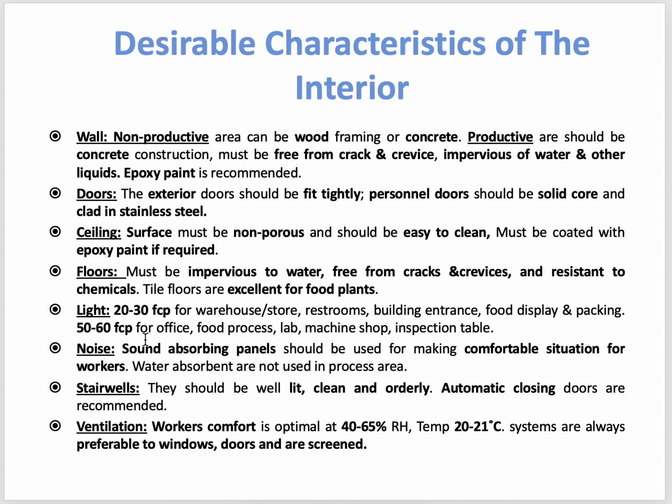Okay, then floors of the plant. Floors must be impervious to water, free from cracks and crevices, and resistant to chemicals. For a food processing plant, tile floors are very good. Tiles are a good choice for making the floor of the food plants. The reasons why floors need to be impervious to water and free from cracks and crevices are the same as for the wall.